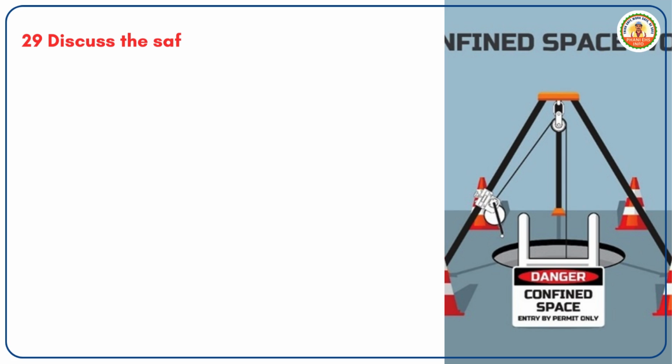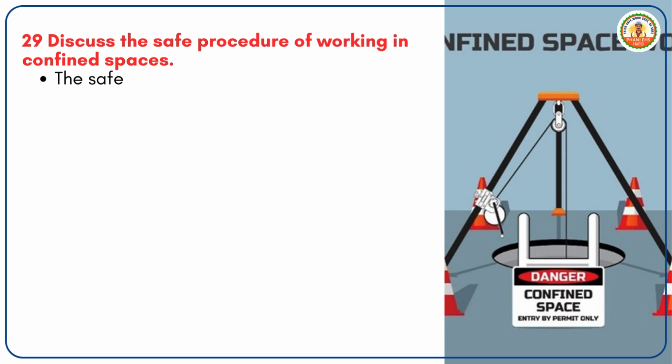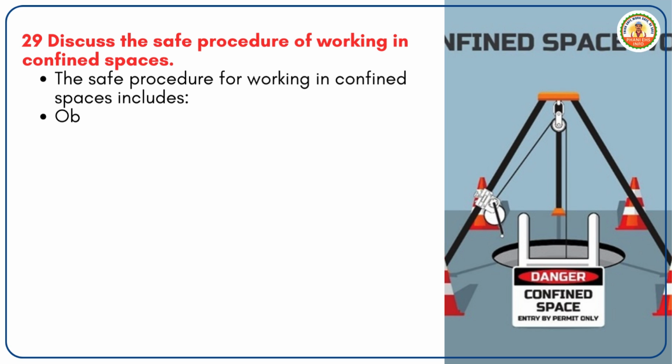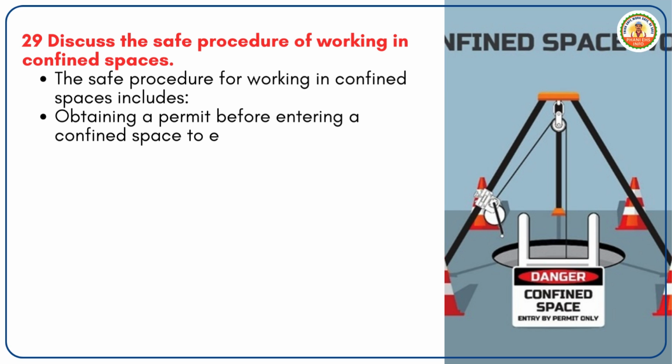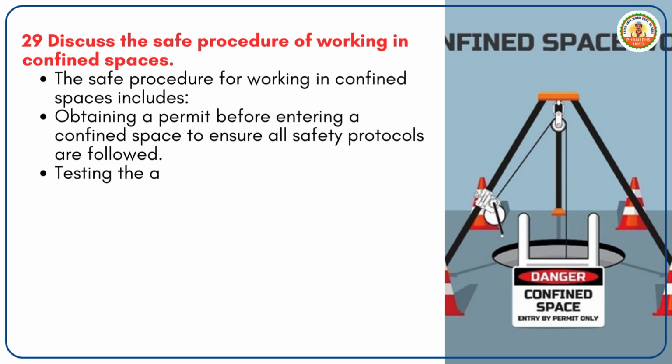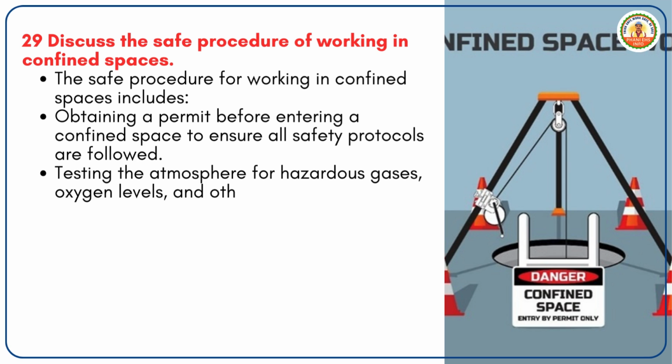29. Discuss the safe procedure of working in confined spaces. The safe procedure for working in confined spaces includes obtaining a permit before entering a confined space to ensure all safety protocols are followed. Testing the atmosphere for hazardous gases, oxygen levels, and other contaminants.